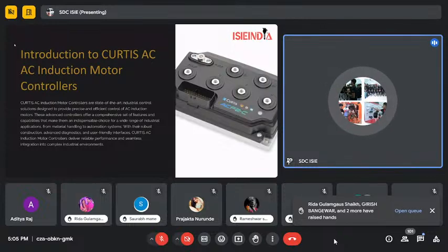It is different from A5, in that in A5 we don't have a reprogrammable option or the ability to evaluate the parameters. But in Curtis, we are getting these features, so we don't use a direct method like FOC or DTC techniques to change the rotation speed of the motor. We indirectly correlate the operations of the motor through the Curtis controllers.